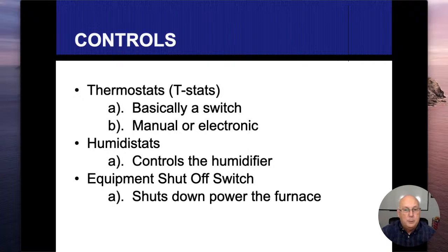When the temperature drops below the desired amount, the thermostat flips the switch on and the furnace turns on. The furnace keeps running until the thermostat says, okay, I'm warm enough, and then it turns itself off. Nothing more than that. It doesn't adjust the fire, doesn't make the fire burn any hotter or cooler. A furnace does what it does, and that's all it does.